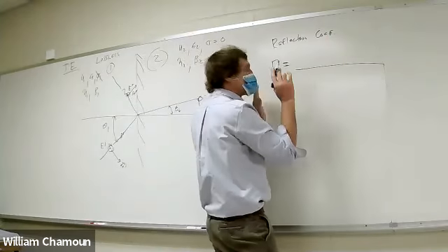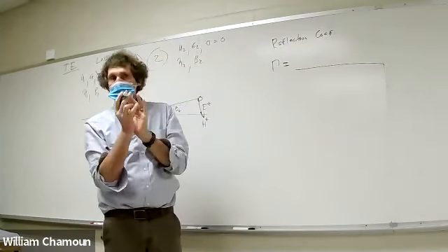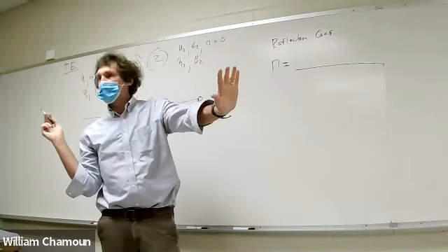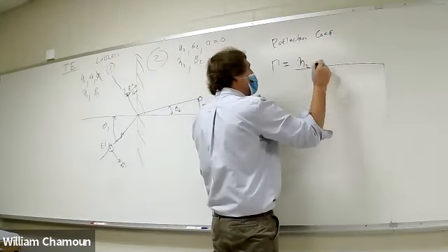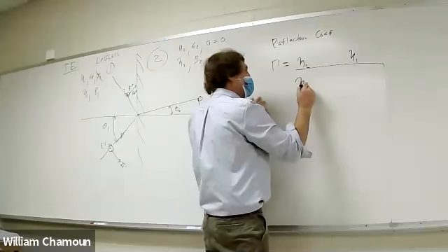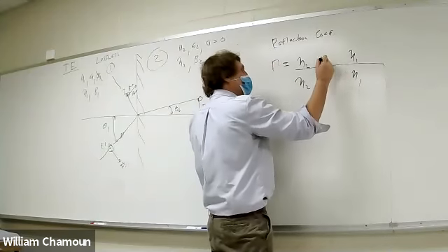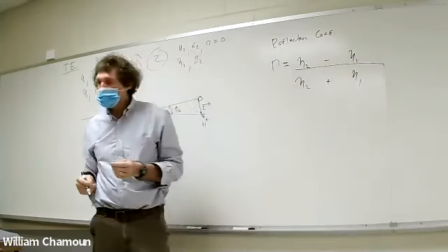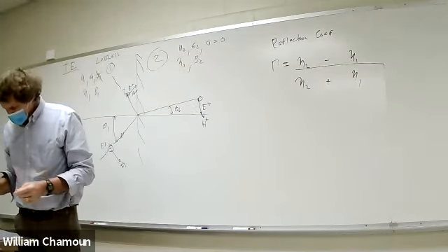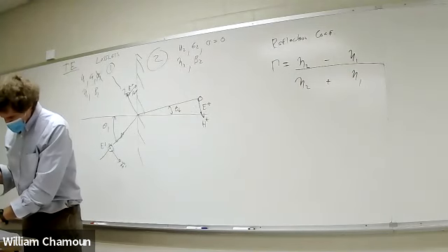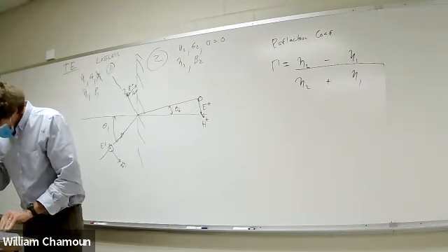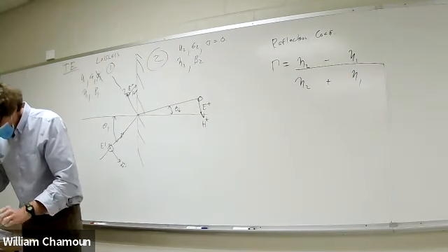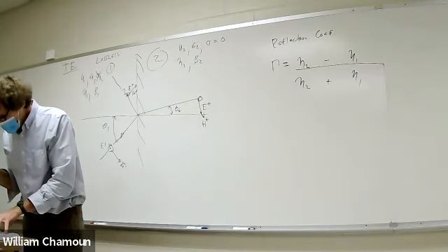So for this one, you always start, now just think about the standard reflection coefficient. It's always the impedance you're going into minus the impedance you came from divided by the sum, right? Same here, you start with putting eta 2, eta 1, eta 2, eta 1. Here there's a minus sign, here there's a plus. Just showing you how I did it. Now, this is in your book for the TE mode. He doesn't actually have the symbol for the coefficient. Well, he does, but he doesn't do the ratio. It's equation 6.133 and 6.134.